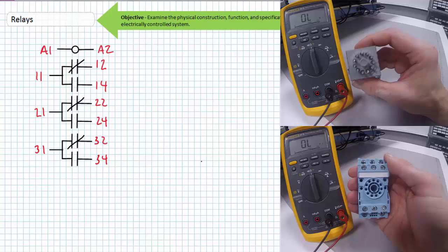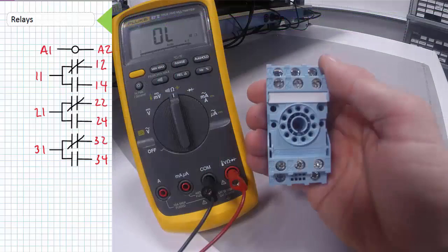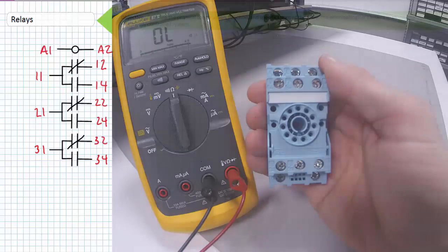If we added another 3-terminal single-pole double-throw switch, this would be an 11-pin relay and obviously require a matching 11-pin base. The base for this specific 11-pin relay has the commons for all 3 switches on the row above the coil, the normally open terminals for all 3 switches on the row above the relay, and finally the normally closed terminals for all 3 switches on the top row. Note the dual numbering scheme is thankfully printed on the outside of the base.